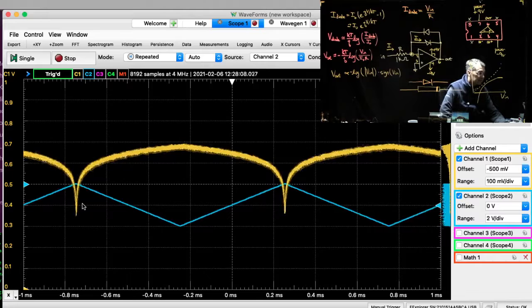So here you can see that a relatively small change in current corresponds to a pretty big change in voltage across the diode for this section down here where it's just barely turning on, right? So we're at about 0.3, 0.4, 0.5, 0.6 volts across the diode.